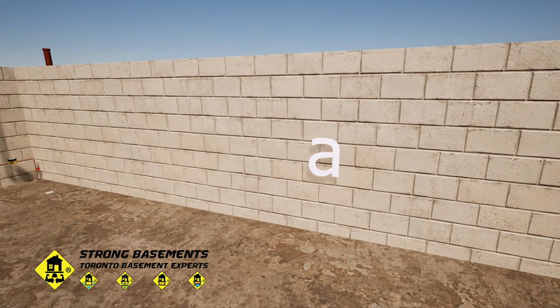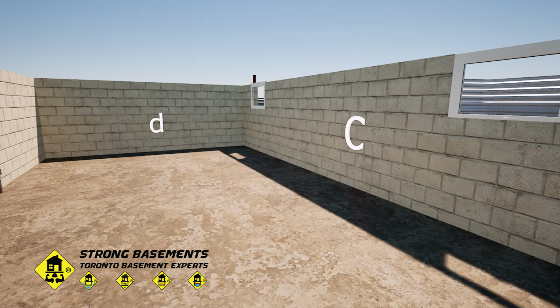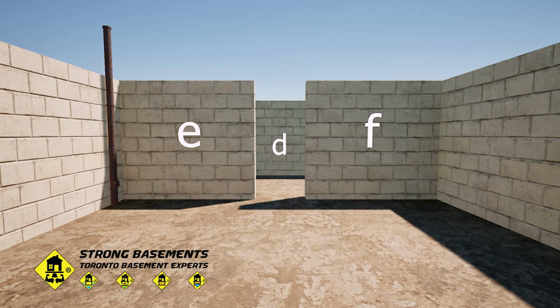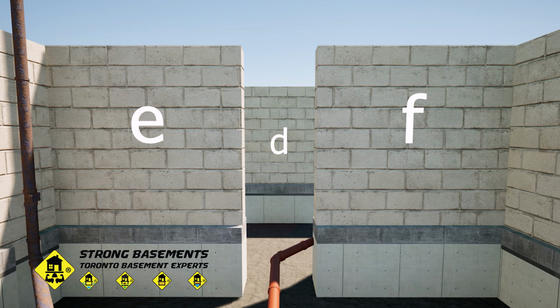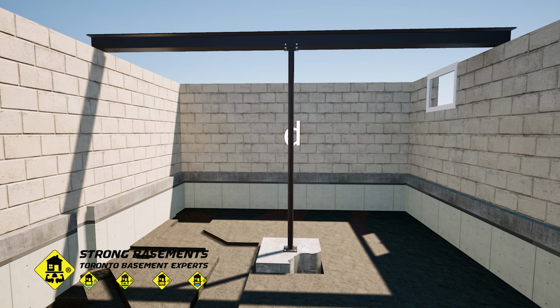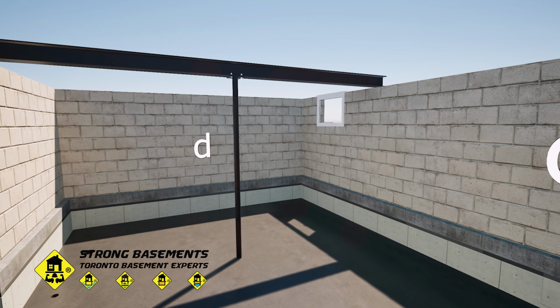Let's start with your current layout. First, measure the total length of all foundation walls. Don't forget to include any interior load-bearing walls as well. Depending on your goals, these interior walls can either be underpinned or removed entirely and replaced with a load-bearing beam and steel posts. This is a great way to create a much more open, modern living space.